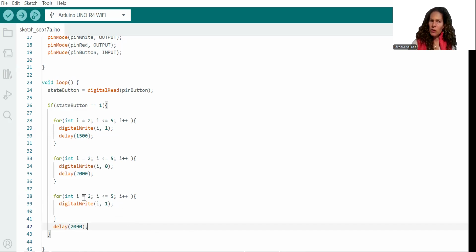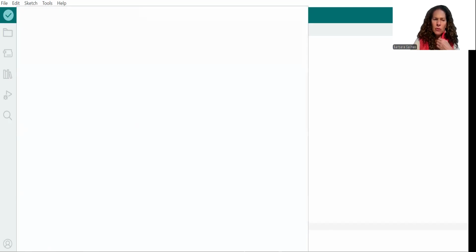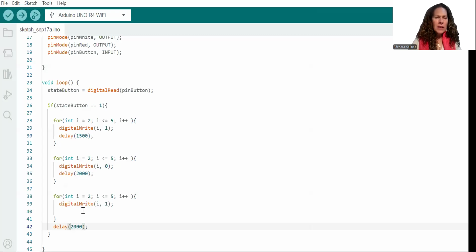And this way, we are going to make the 4 LEDs light up, all of them at the same time, and they are going to remain on for 4 seconds. Instead of 2000, 4000, okay? And remember, this last curly brace is closing the if. Don't touch it, it is important. And then place the pointer of your mouse after the semicolon, where we have the 4000 milliseconds.